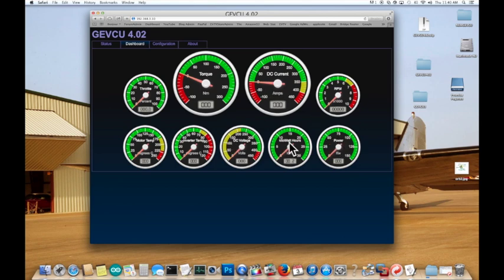And this will keep track of your kilowatt hours, how much energy you've taken out of your pack. That value is actually cumulative each time you start the car, and it'll save it to EEPROM, so you can start and stop a dozen times, and this value will just keep going on up. But it resets.